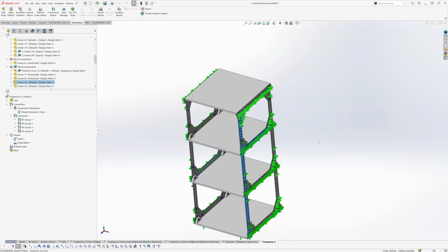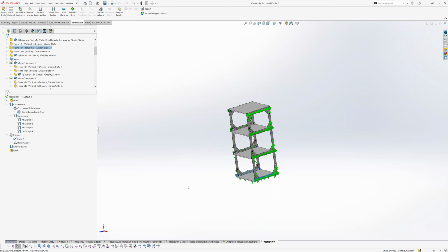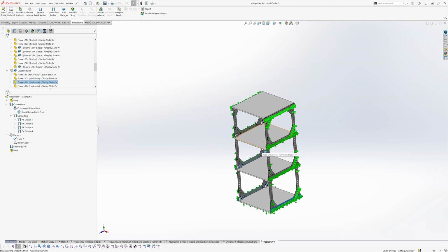Okay. So at this point, we're pretty good on this study. Looking at the study, we've got our roller slider constraints, our fixed, and our pins. So this really should be constrained enough to go and run our study now. It's obviously good to look at everything.